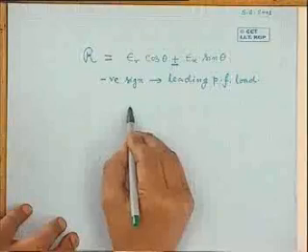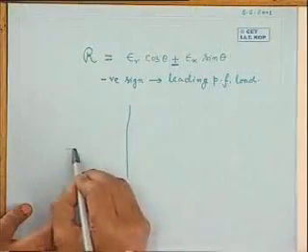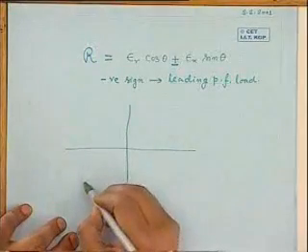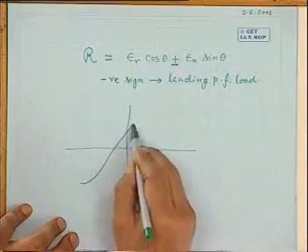See, from no load, whatever is the voltage, with full load at a given power factor, if I want to maintain that voltage, it can occur only at a specified power factor. Otherwise, it will change. But as I have told you earlier also, the power factor of the load is generally lagging in nature in the power system. Now, if you sketch this regulation curve, you will get a curve like this.